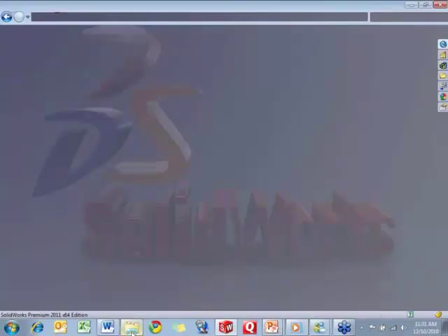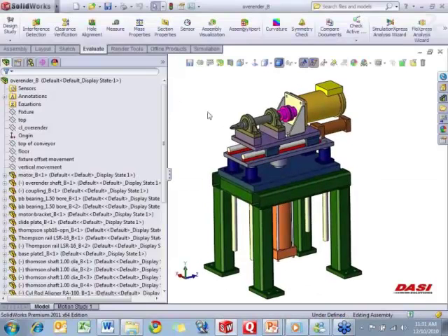All right, now let's take a look at assemblies. With assembly documents, I think interference detection is something that pretty much everyone is familiar with. You have the ability to select the entire assembly to find interference, or select a number of components for interference detection. And as you pick through those interferences, you can change the options down here for visibility of the non-interfering components. We can, for example, make those hidden. So as you switch between these, it only shows you the interference between those parts.